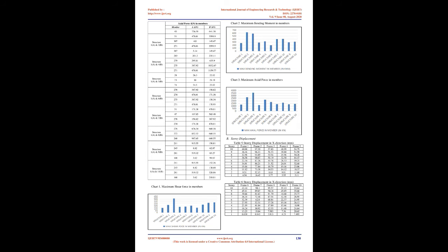Frame 2 has first and second stories soft. No floor slab has been provided, which makes these 2 stories less stiff, i.e. softer. Frame 3. This frame has fourth and fifth stories soft. No floor columns, vertical, have been provided, which makes these 2 stories soft. Frame 4 has heavy loading on third and sixth stories. These 2 stories of the building, i.e. third and sixth stories, carry heavier loads, hence making the building irregular.